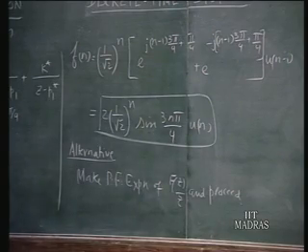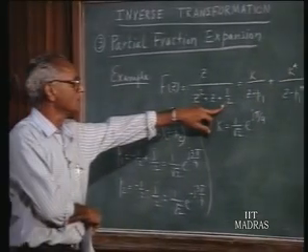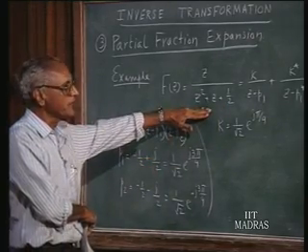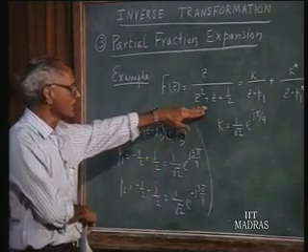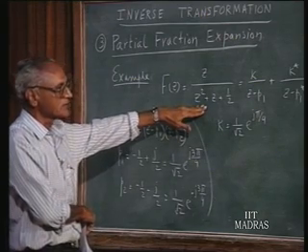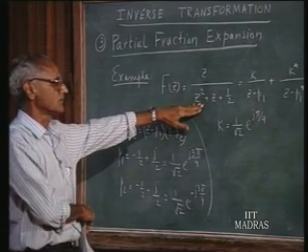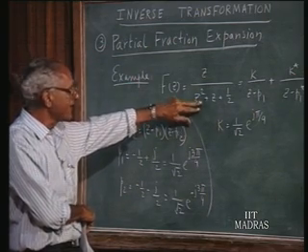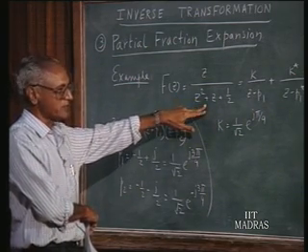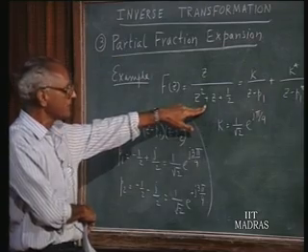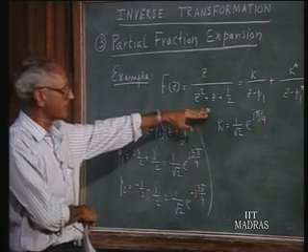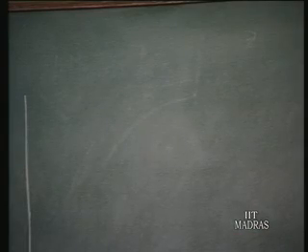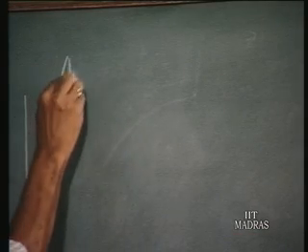But then whenever you have quadratic terms here and the poles are complex conjugates, then we know that this is associated with a sinusoid term in the discrete time function. Therefore, one can identify this with what you would expect when you have a damped sinusoid, and then get at the solution in a much more direct fashion, and that's what I would like to proceed with now. Okay. So as a third alternative,